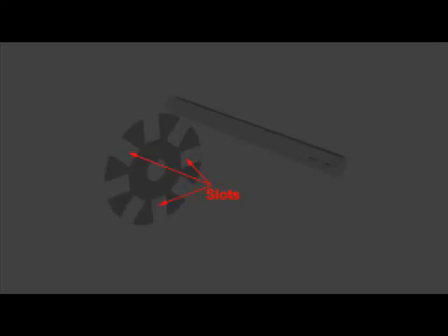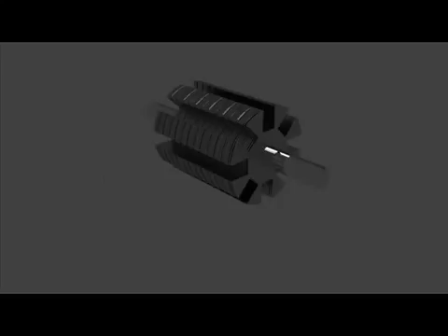The slots are either die-cut or punched on the outer periphery of the circular core. Stamping or the keyway is located on the inner diameter. The slots are normally open type and usually placed parallel to the axis of the armature, but are also sometimes skewed at small angle to avoid vibration of teeth.